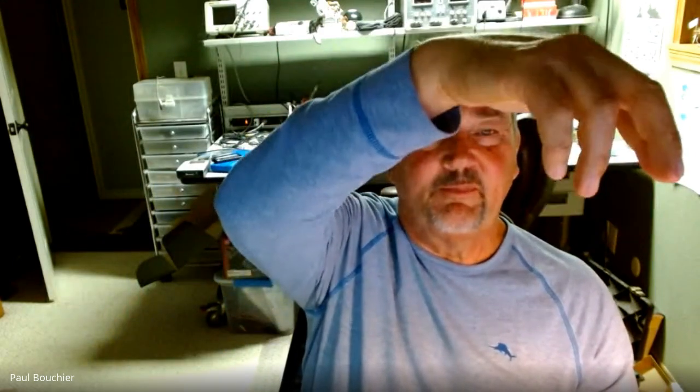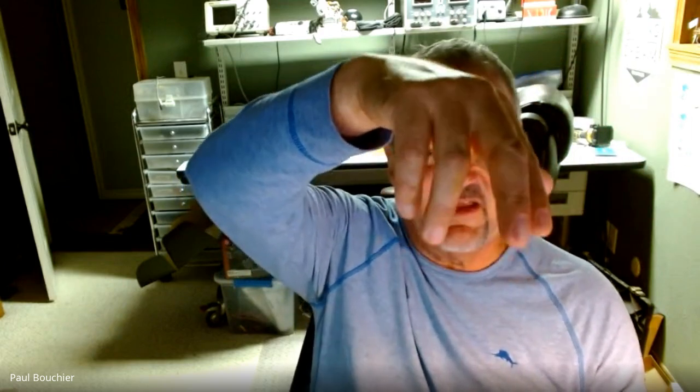What you do is you find a map, and there'll be 3 or 4 markers in a 10-mile radius. They're just everywhere. You find one that you can actually find, then you sit your base station over the top of it, and then you go to some reference point on your site that you want to reference to. So for Mickey, that could be wherever he's got his mowers working, and that gives you an offset from that known point.